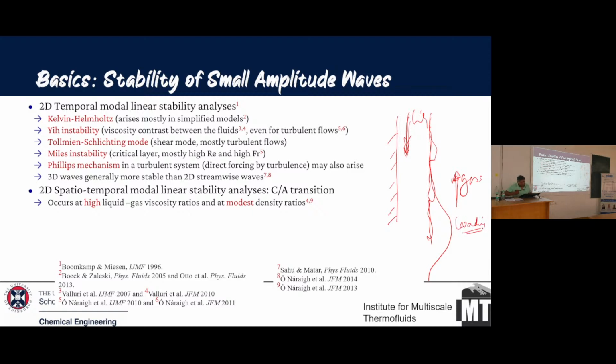Now, if you keep increasing your gas flow rate, the waves then travel upwards. That is called the flooding condition. In the flooding condition, the waves are traveling opposite to the direction of the liquid. This is where the waves start growing against the flow. They go over the flow and flood the entire domain, and that's when your column becomes inoperational. So when you're operating a distillation column, there is a limit. Bigger gas flow rates have the advantage of big waves, which give more mass transfer and heat transfer, but the limit is the flooding point.